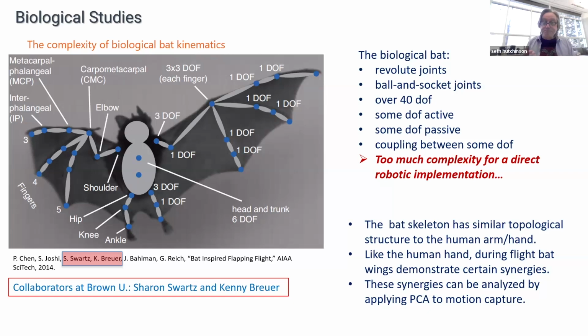That reminds roboticists of the concept of synergies that have been very popular in the grasping community. If you think about grasping an object with your own hand, one of the things you'll notice as you start grabbing different things is that there aren't that many interesting things you do. You grab a bottle like this, and it's a small degree of freedom motion, even though there are a lot of degrees of freedom involved in the action. Basically, closing my fingers is a one-dimensional manifold in the configuration space of my hand.